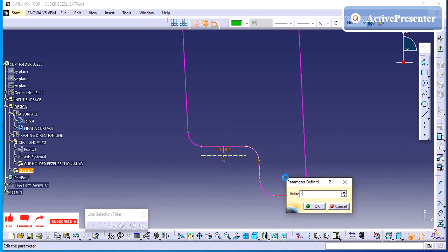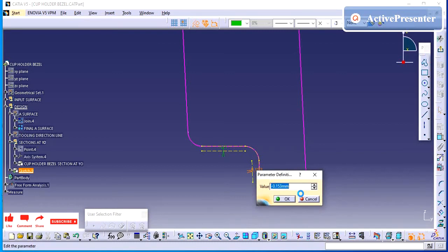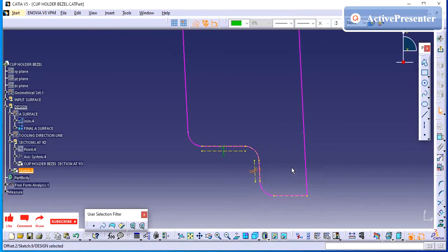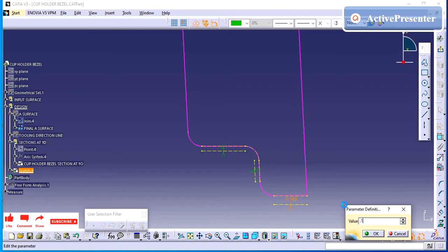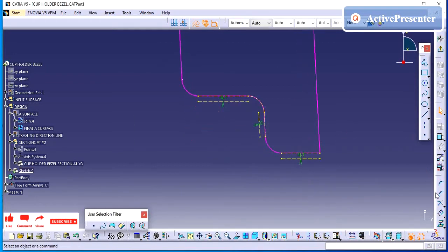So make sure how your part is going to sit with the environmental part. For easy understanding, I am going to maintain the 0.1. If you see, instead of 0.1, it will have the touch condition in reality. So due to gravity, it will pull the part down so that it will just rest on the mating part. For easy understanding, I am just creating the profile with 0.1 mm clearance. If we are creating with 0.1 also, it is okay, it will have some safety.